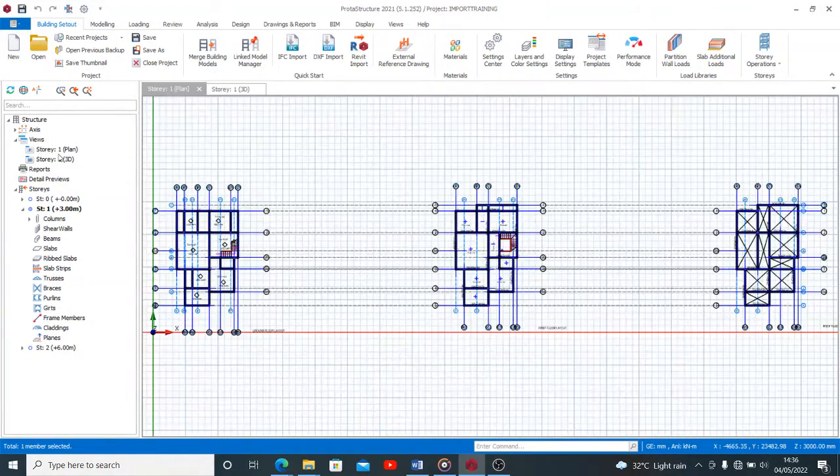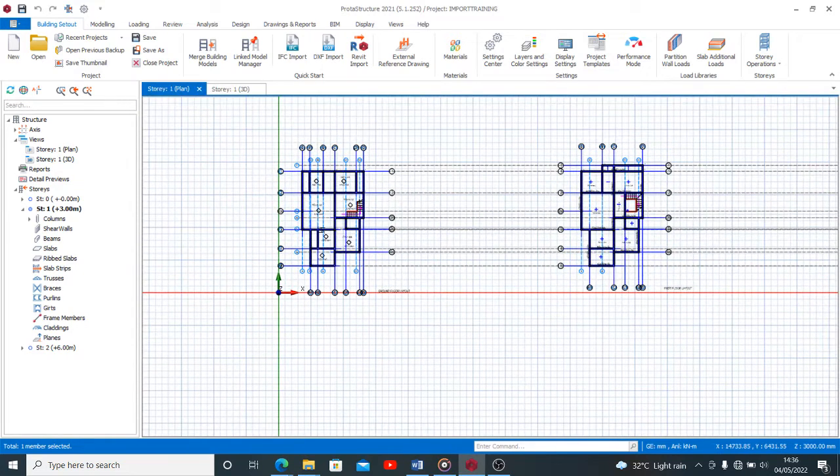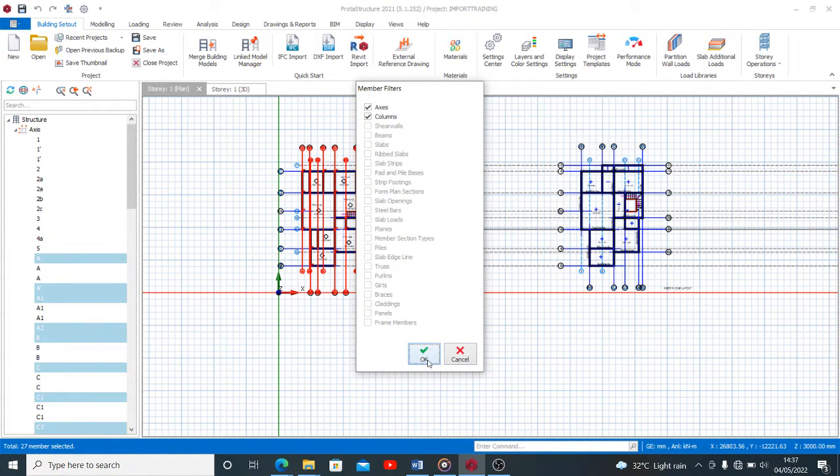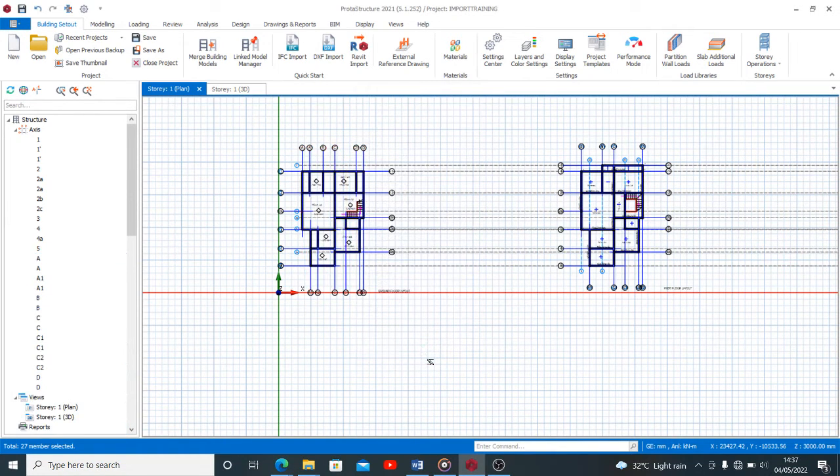So let's get back to our plan. What we'll do now is eliminate all components of the ground floor, since we have the understanding that all our vertical components would start from the floor that is above the present one that we want to work with. Let me just show you that practically. I'm taking out all the elements on story 00, the columns and the axis and whatever it is that I need to.